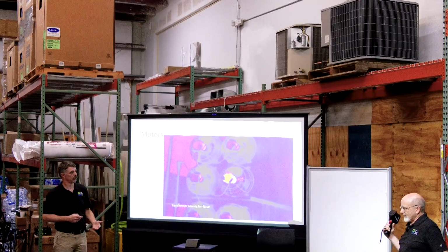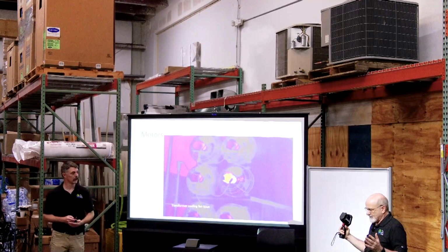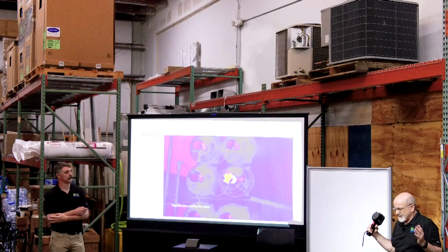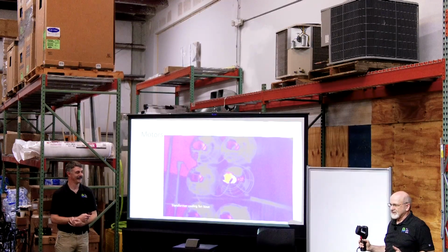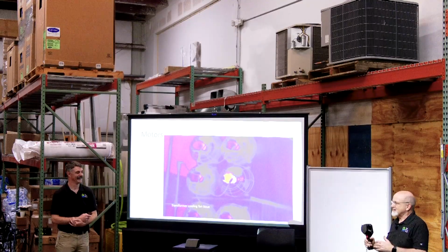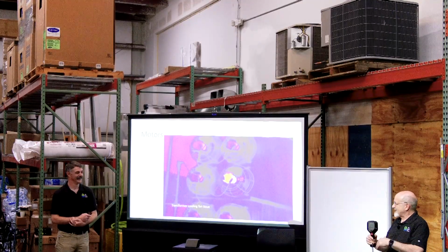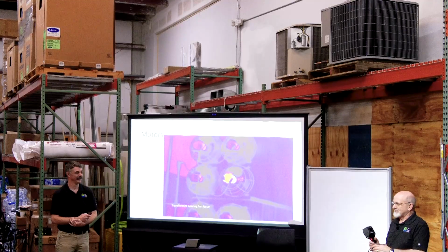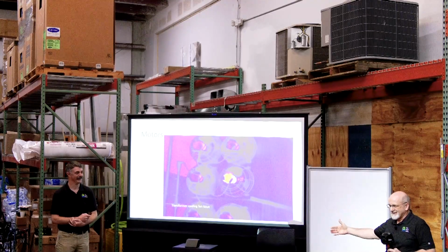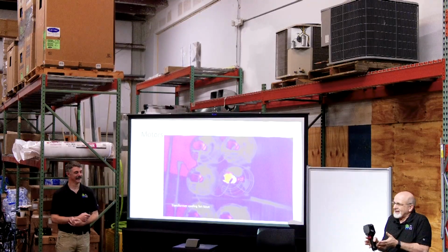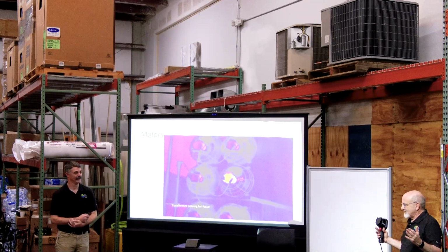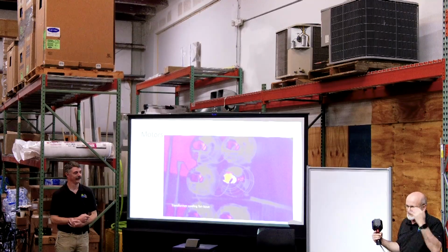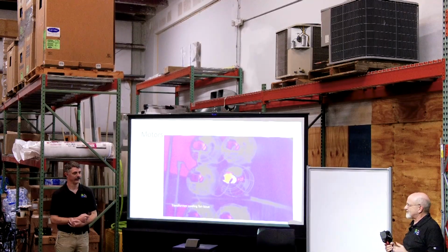Another example would be I had a friend who was remodeling a house, a little lake house, and walked around with a thermal imager before he had any insulation in the walls. And he said, wow, this is great, because it's not showing any thermal defects. It's because it was the outdoor temperature. So he wasn't really trying to hold any heat in or keep any heat from leaving. You got to know more background. Use your technical mind to ask these kind of questions.